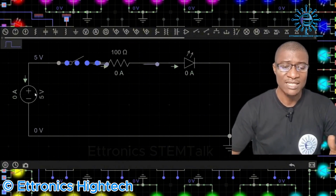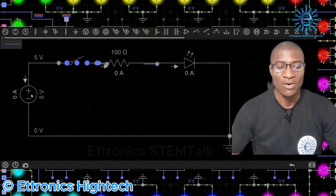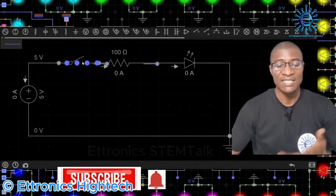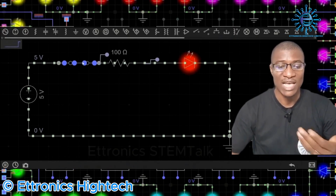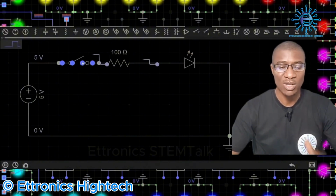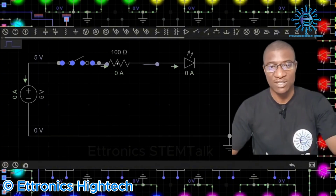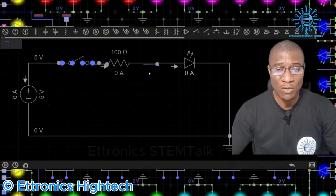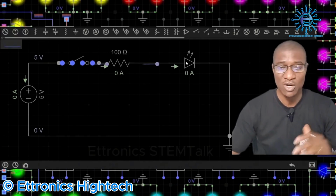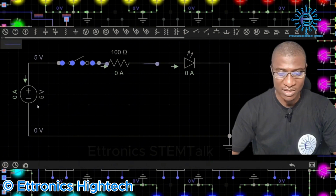So this circuit has a power source, which can be a battery or a DC power supply. And it has a switch, which when I close, it allows current to flow in the circuit. And when I open, it cuts off current supply in the circuit. And we also have a resistor. Here we are using a 100 ohms resistor, and we have an LED which glows when the appropriate current and voltage enters it. And then we have some connection wires here, all right?